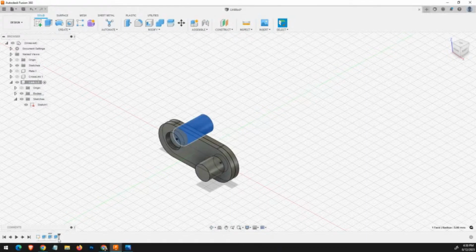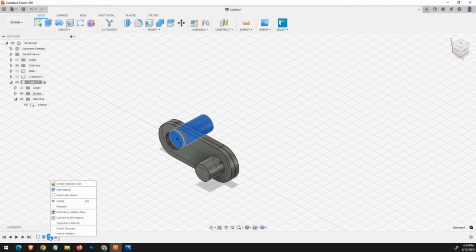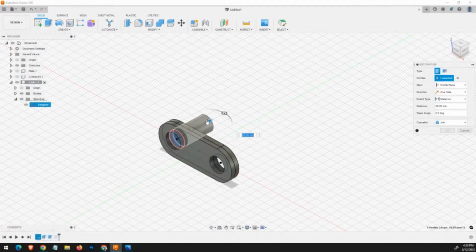And look down here at where it is. So, you see it has a highlight here. And when you hover over this extruded feature in the timeline, here it is. Okay? So, if this is your case, because earlier I didn't put the dimension, now I will correct it. So, here, right-click and edit feature. So, you can now put the correct value here.